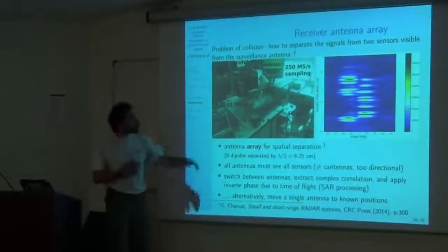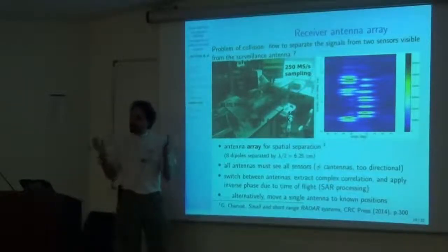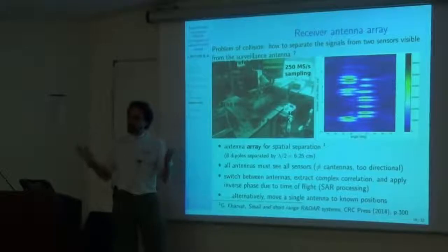So just to show you what I found fascinating, before going to Japan, I was not familiar with the fact that, as in the network analyzer where you have no reason to measure all the frequencies at the same time, for DOA analysis you have no reason to measure all the antennas at the same time. You might measure antenna number 1, then number 2, number 3, and then you do the processing of all this data that you collected.